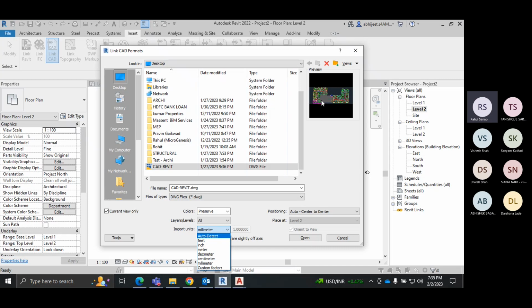No, we are importing a 2D layout. We are not importing any kind of schedule. Supposedly, if we have taken a door in the CAD and a schedule is given in the AutoCAD drawing, will that also be imported and come up here? No. An AutoCAD schedule is only 2D data, just for information. We cannot convert any schedule inside the Revit environment, because we need to create a 3D of it, right? Yes.